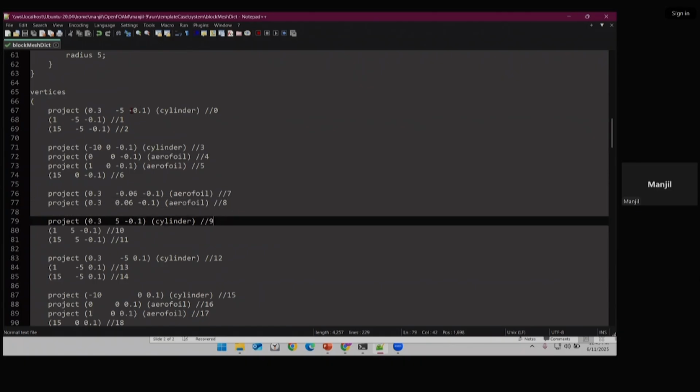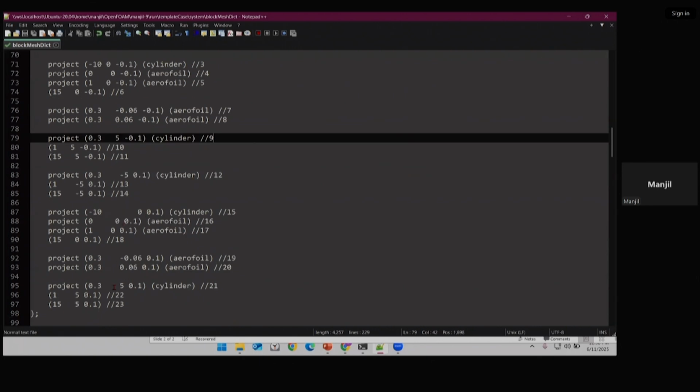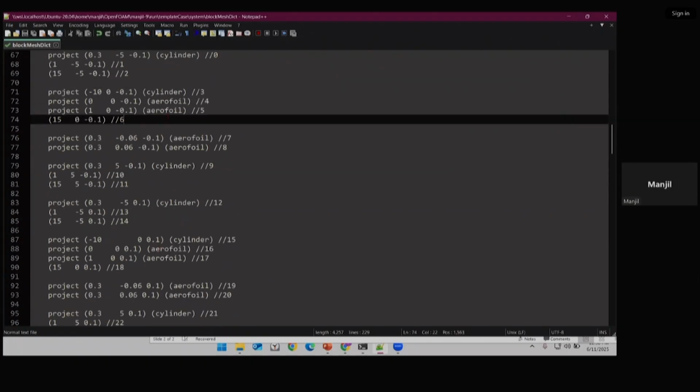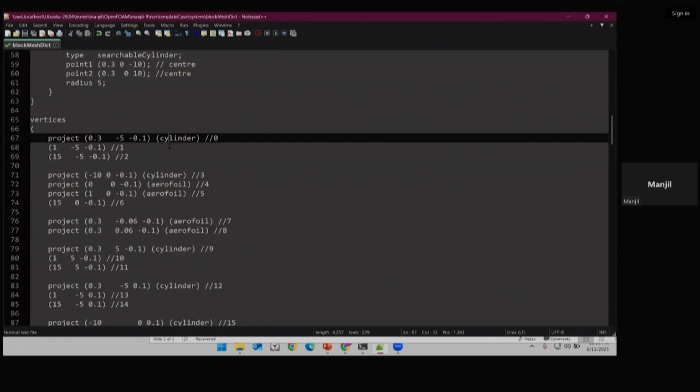So you move in the positive z direction, that is, first assign the low value coordinates. I have used minus 0.1, you could have also assigned 0 and 0.1, or 0 and 0.2. But if you go from 0.2, first assigning the 0.2 coordinates and after that the 0 plane, then this will require the convention to change to clockwise direction. You can try this on your own and play around with these numbers, then you will understand what I'm saying here.